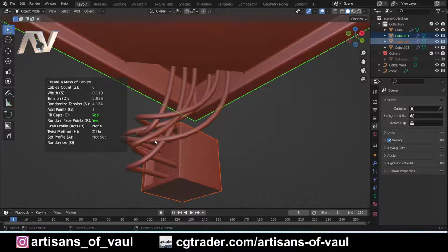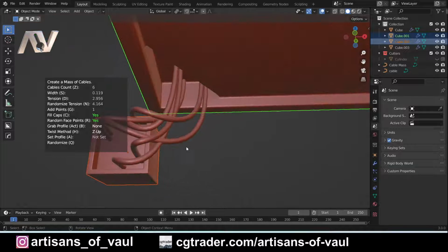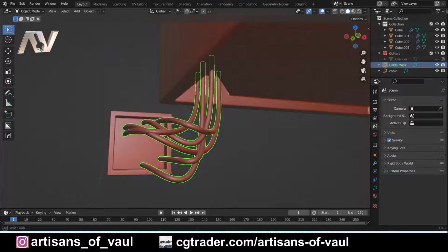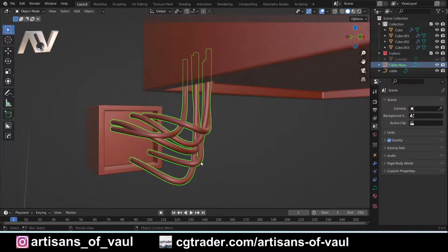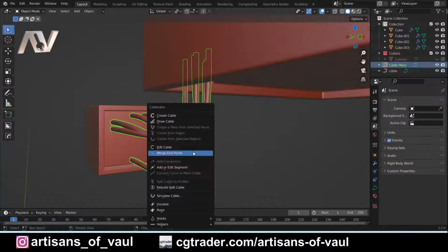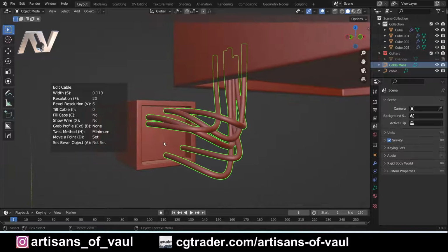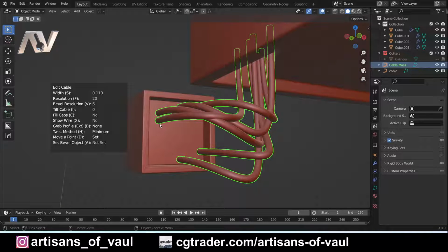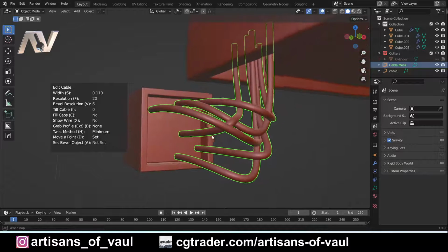And sometimes you want these bits interconnecting because it means that they're going to support each other when you're 3D printing them. I'm going to click off and we've got everything there. I mean, it's just so good. And again, Shift Alt C, I can still edit all the cables. For example, and this is a really good one, if I go near a cable and press D, it will move that tip. Go to that one, press D, I can move that one. In fact, if I go back to that one and move it there, it's suddenly not cutting across everything as badly.